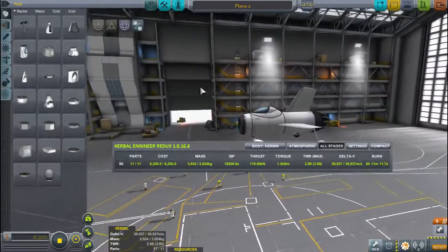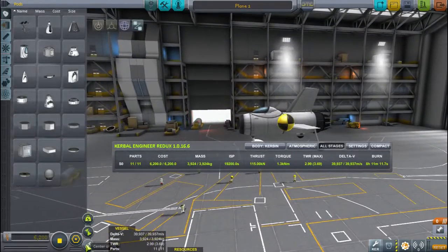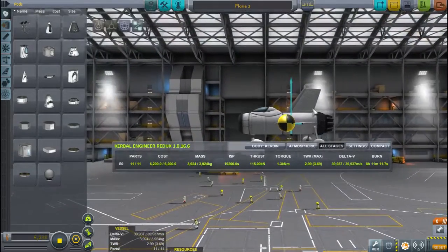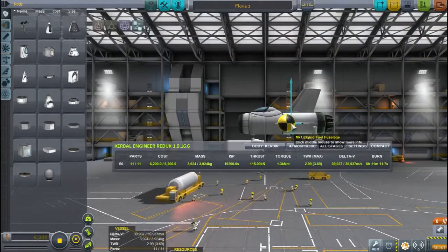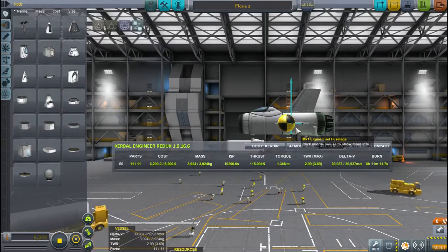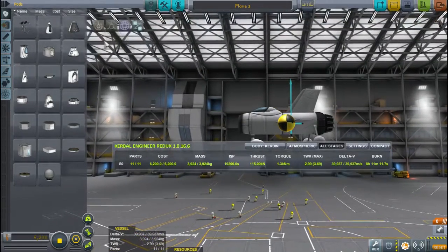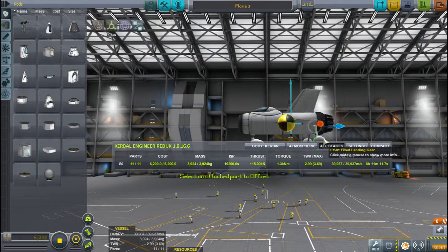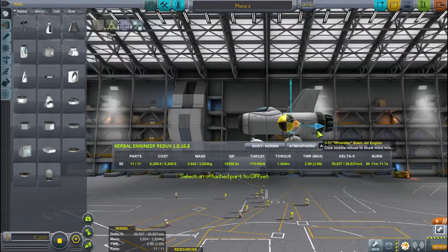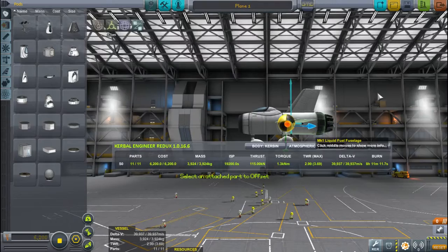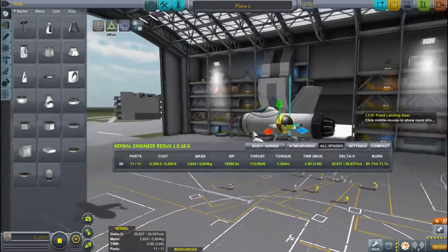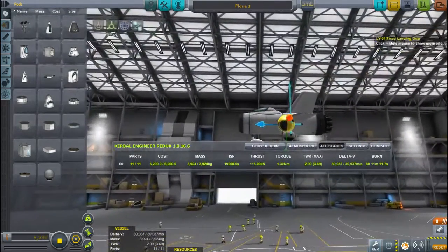In this case in particular, whenever we're pulling up, this is pushing down on the wheels, and so all of that downward force is being lost. It's being absorbed through the wheels. If we moved these wheels forward just a little bit, maybe like that, into where the center of mass is, we will get a pivot going on.